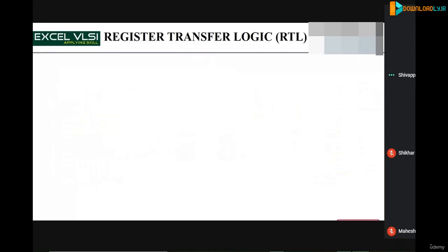And register. What is a register? So the basic register can be realized like 1-bit memory. Okay, 1-bit memory. Any flip-flop can represent a register. Of course you will use 8-bit, 32-bit, or 64-bit today. So that way you will use that many registers. So that's how the name came. And it's a design abstraction which models the synchronous digital circuit. So the moment you say register, it is synchronous, we say.